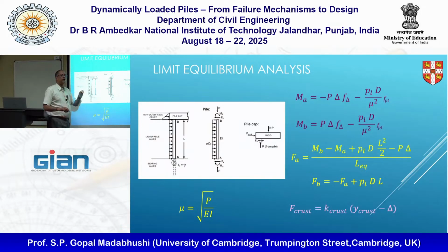These layers are always going to be fairly of limited thickness, maybe 1 to 2 meters. So although I am applying passive pressure, that triangle is going to be fairly small. In the simplest of cases, we can say the liquefiable soil, as it is trying to go towards the pile, is applying some kind of uniform pressure.